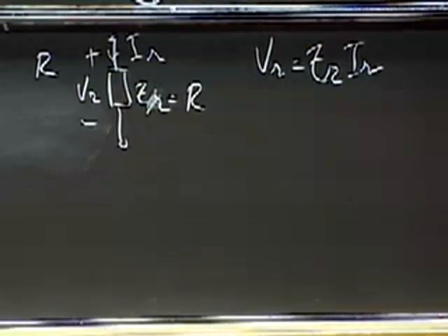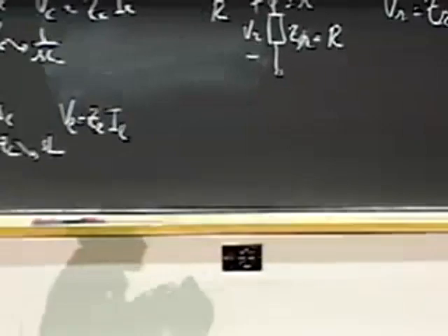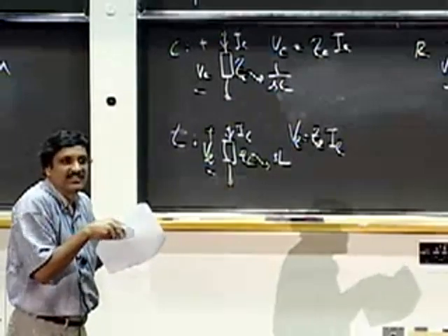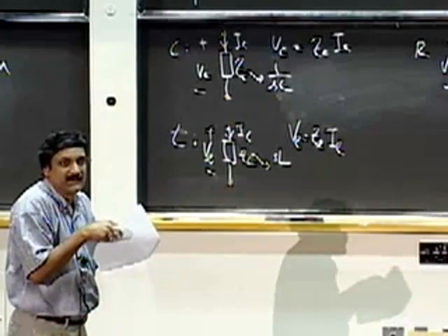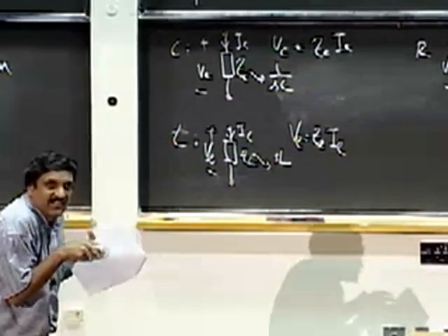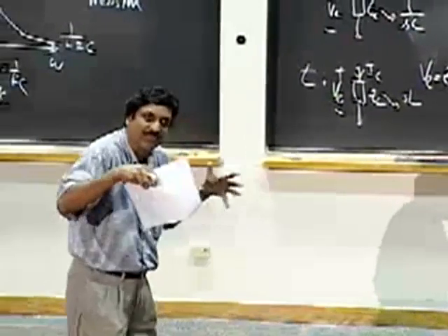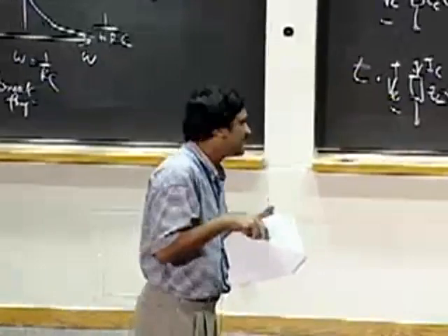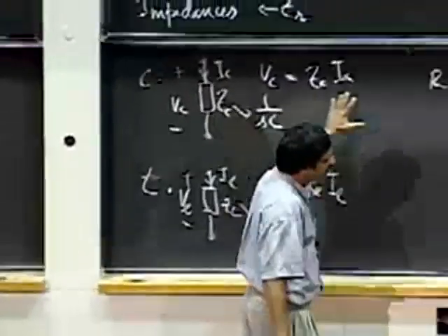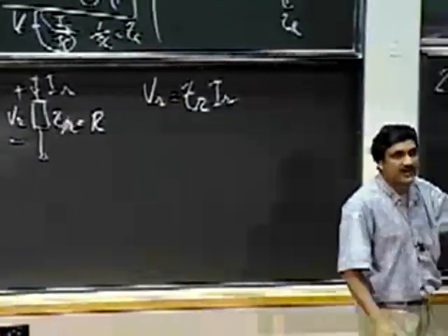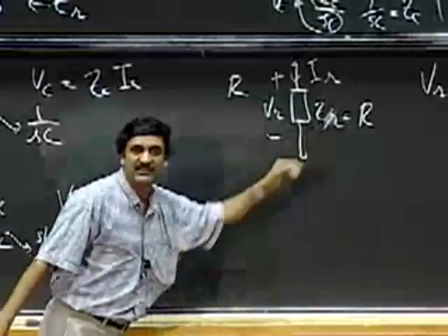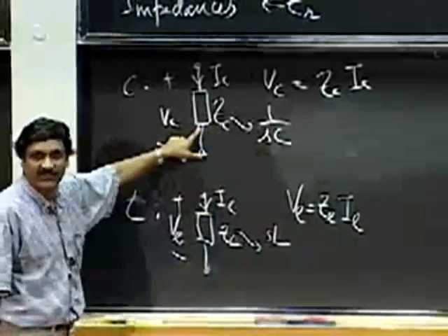Okay, so what I'm saying is that if I constrain myself to the region of the playground where my inputs are complex, something like Vi e to the j omega t, exponentials in that little region of the playground now. I've been focusing more and more on small parts of the playground, so I'm kind of boxed in right now. So in that region of the playground, this applies. I can replace resistors by impedances, capacitors with impedances of value 1 by SC.